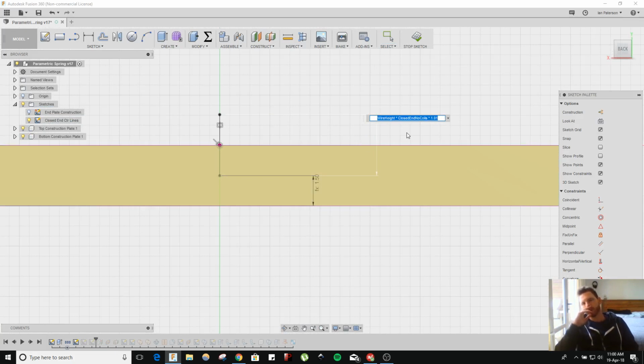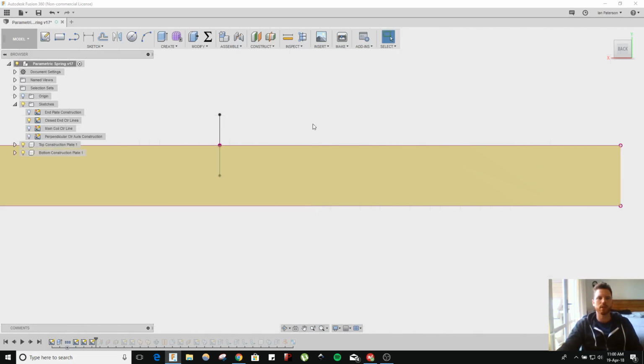The wire height, because obviously you need 1 wire height difference so that when you wrap the wire around it doesn't clash with itself. And that 1.01 is just so there's a very small gap between the 2 layers of wire, so that they don't touch and create a point or line volume geometry intersection that the modeling solver doesn't like.